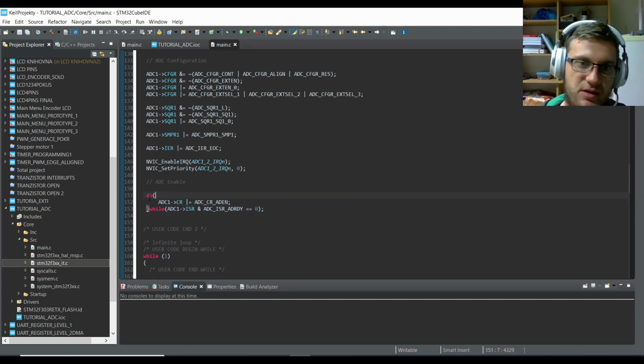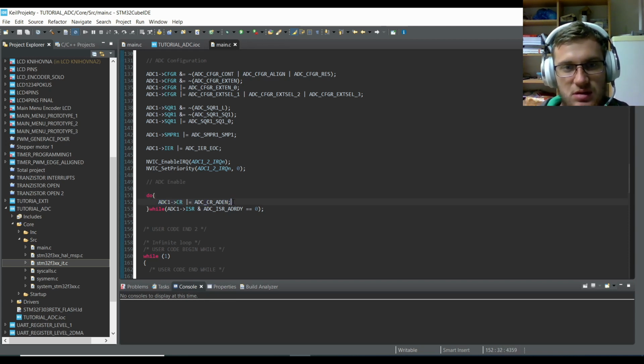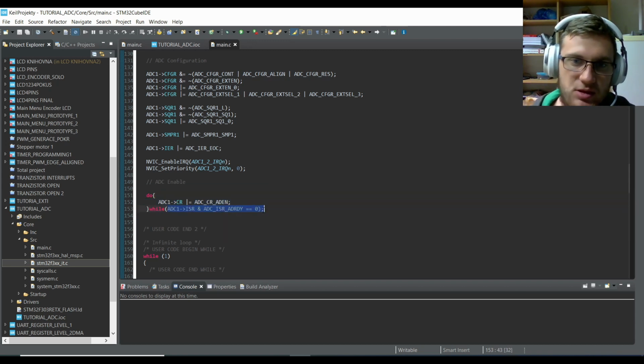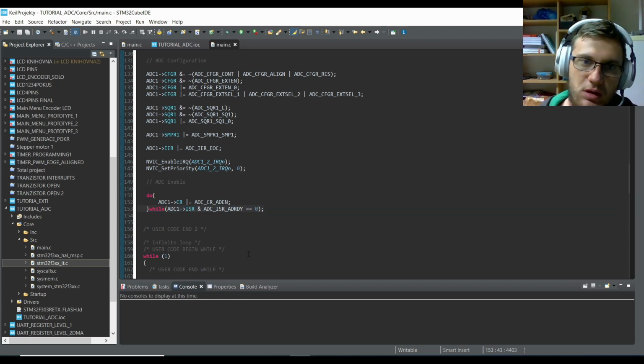You may ask, why did I use a do while loop? It is because it saves clock cycles, and usually during a configuration or startup, programmers use the do while because it at first executes the code inside the do brackets, and then it checks if the condition is true, and if it is, it can escape and continue in the program.